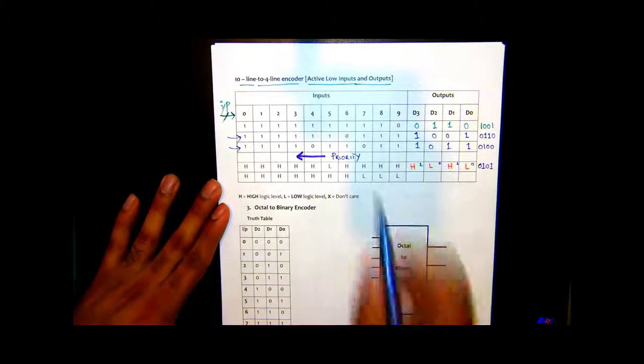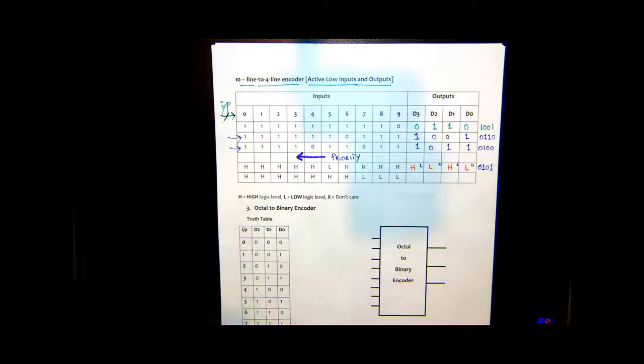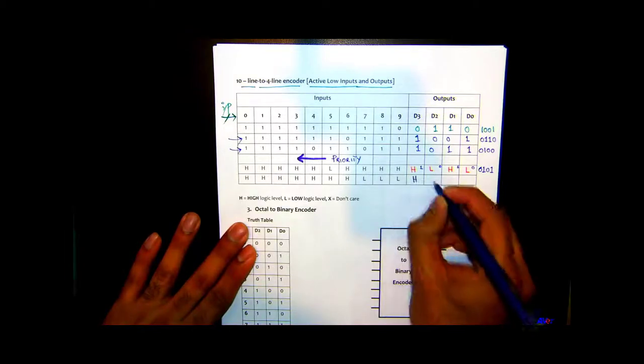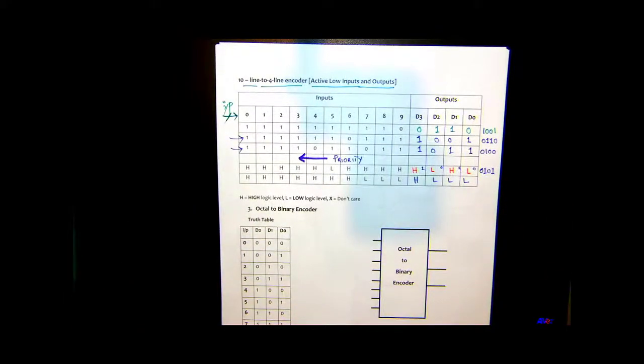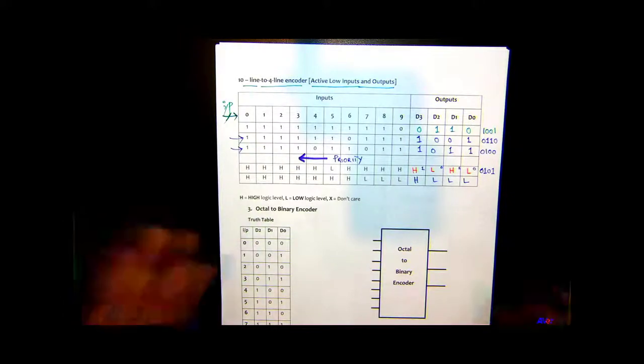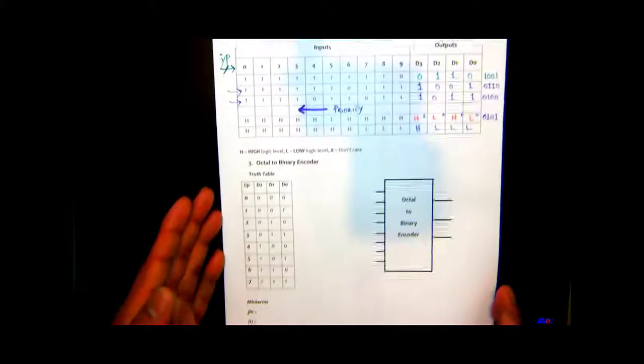What about this right here? We got 7, 8, and 9 both set to low, and the priority actually increases moving from right to left. What would be the output here? H, L, L, L. Correct. 7 makes a code of 0, 1, 1. So inverted, you get 1, 0, 0. 1 is high, and 000 would be 3 lows. Okay, so that was just a.